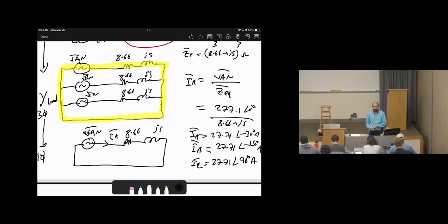So in summary, to deal with three-phase AC circuits, whenever you see delta, remove it. Remove it like what? Convert delta to Y. Then deal with the circuits, converting three-phase to single-phase. After that, do your simplification. If there are some series elements, parallel resistors or impedances, do whatever you need. Okay? Any question?